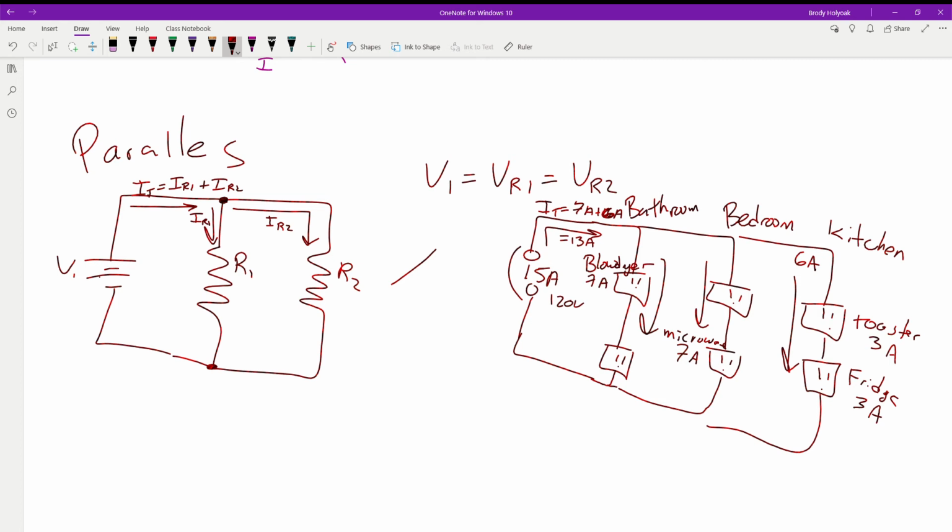So the thing is, you have to shut your main power off, and then what it does is it actually sends a signal in that line. It usually sends a pulsing AC signal, so that when you pick up the receiver, you're detecting this change in current, and that's what makes the receiver squawk. That's good for tracing out lines if you have your power shut off to start with. But if your power's on, it's kind of hard to find it sometimes.